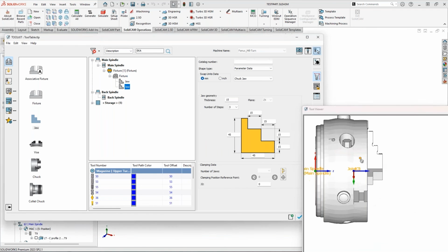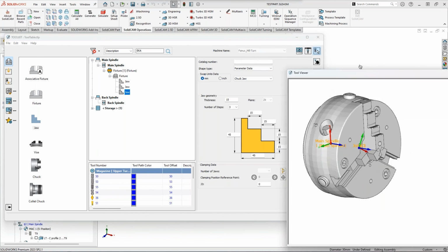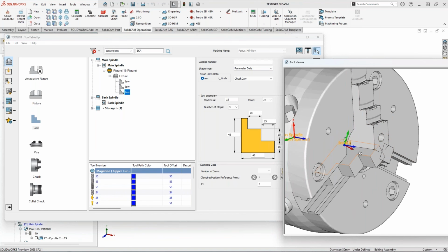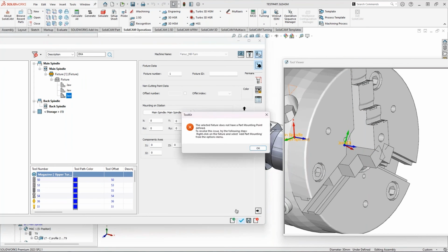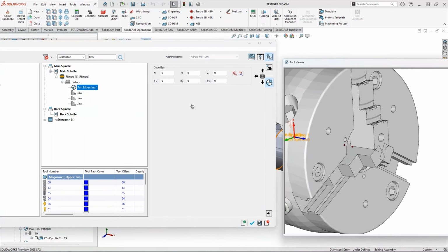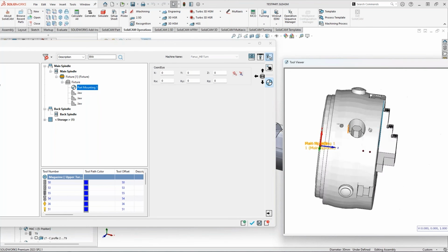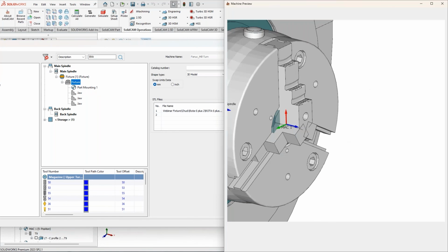So I just drag it. This is parametric, and another one, if I drag it, it will be parametric as well. So obviously I have 3 different jaws. So this can be parametric, this can be 2D, this can be 3D, different profiles. It's up to your imagination what you want to do with it. But now you can also note, if I go over here, I'm just going to accept it. Oh, I have no part mounting. Let me just define it quickly, part mounting. And it was on, I forgot the value. My brain doesn't work for it. So it's 81.5 exactly. I'm going to accept it.